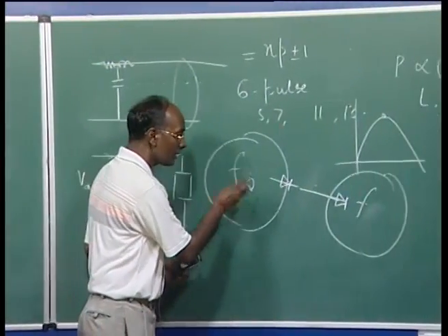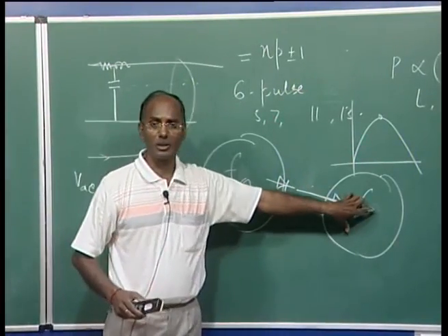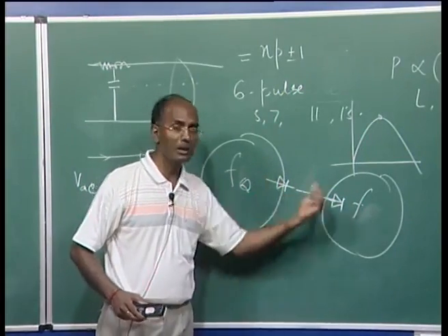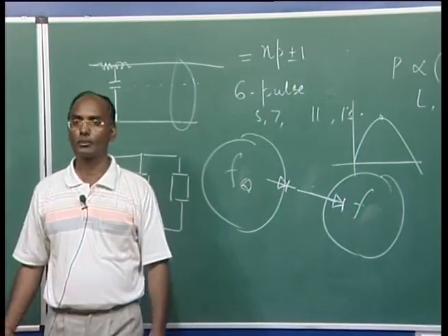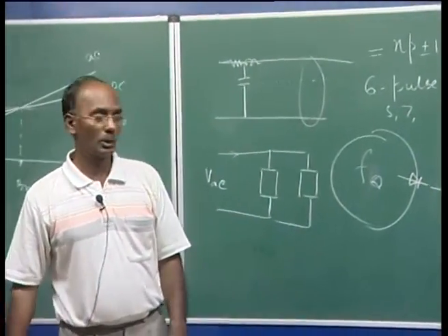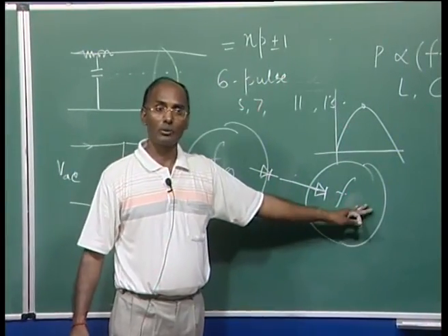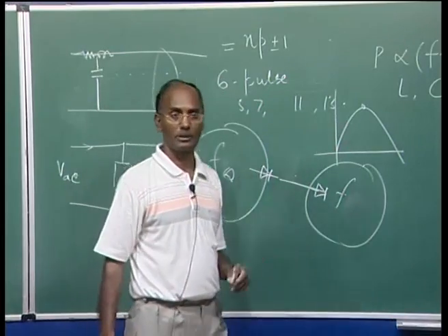But sometimes during an emergency condition, let us suppose there is a fault or some problem in this system, temporarily we require some reactive power support from another region. And with a DC link you cannot provide that reactive power support. So it blocks the reactive power from one end to another, and sometimes we require reactive power to flow from here to here or here to here, and that is a problem with the DC system.